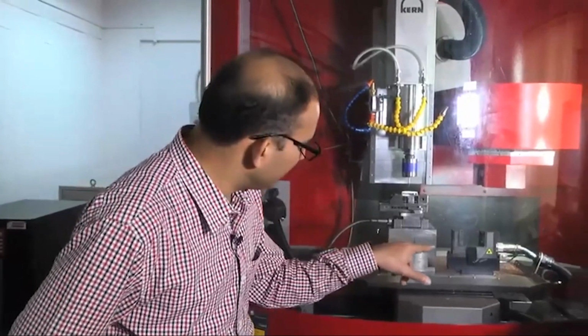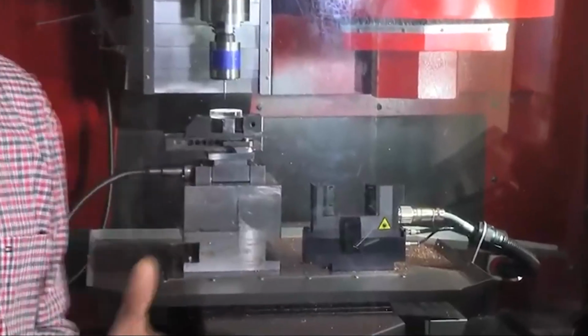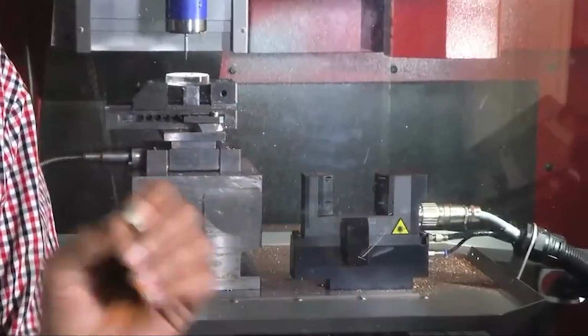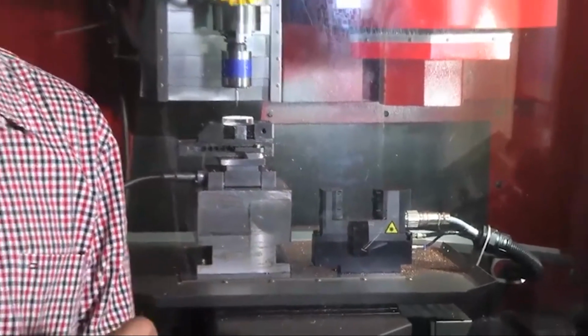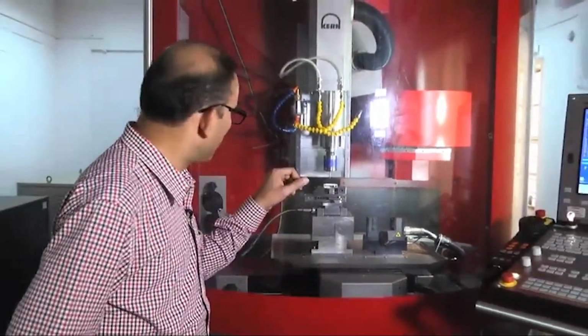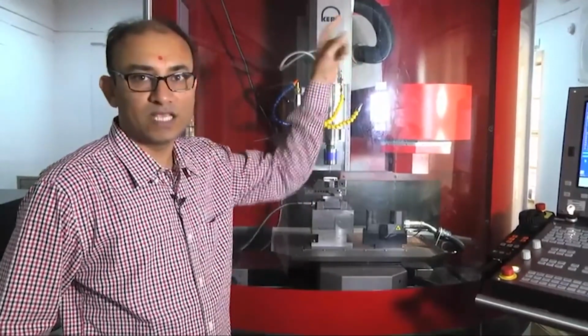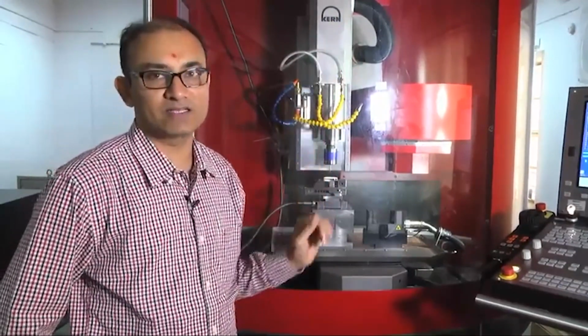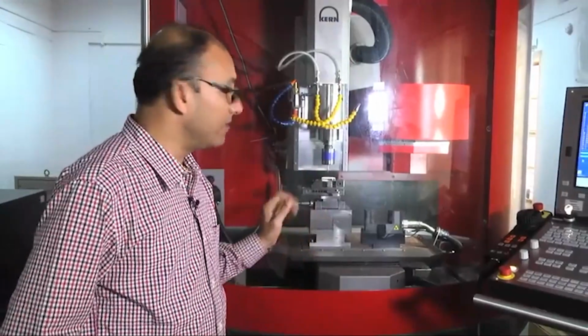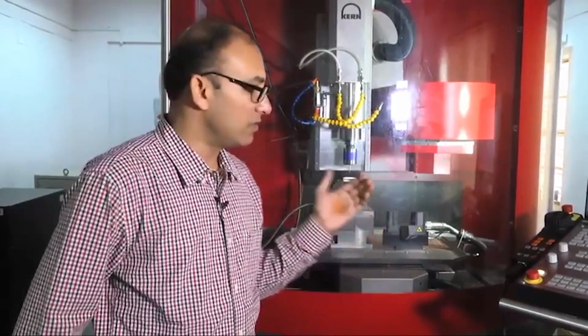The other thing, black in color and located here, is a laser based tool measurement system. Here, for micro end mill cutters up to 30 micron diameter, you can measure length and diameter. And this particular probe is a non-contact probe. It has an infrared sensor located just above it, so you don't need any wires connected. The advantage of this machine is that once the component is fixed inside, you can do all this measurement, of the workpiece as well as the tool, without touching the surface.